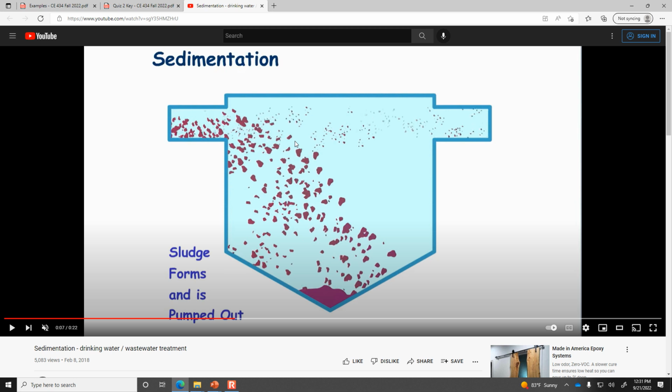where the key is that we have to manage the velocity coming out of the tank, because if the velocity going out of the tank is too high, then it will suck the particles into the outlet. So we need to have some sort of a design that is a calm zone where these particles can settle downward, and then an effluent design that doesn't disturb that calm zone. Now, this is showing an important point, and that is those particles don't all have the same diameter.